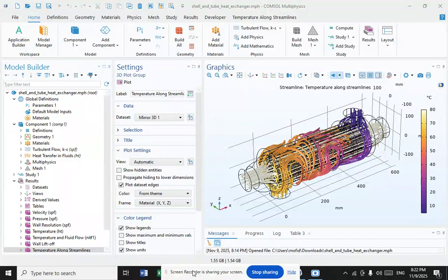And what about the types? By maximum operating temperature, heat exchangers can be divided into low temperature and high temperature ones. The former work up to 500 to 650 degrees centigrade, depending on the industry, and generally don't require special design and material considerations. The latter work up to 1000 or even 1400 degrees centigrade.